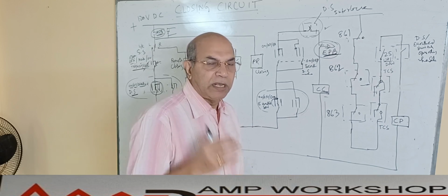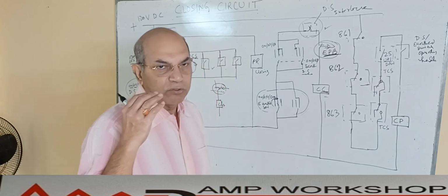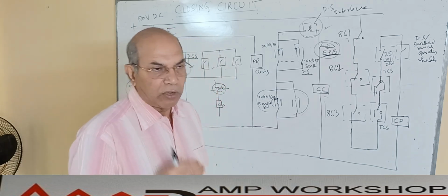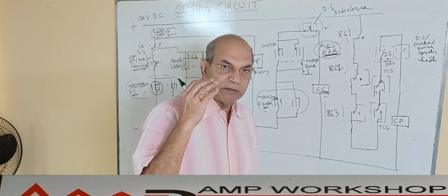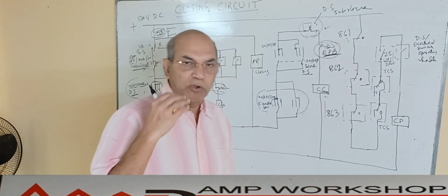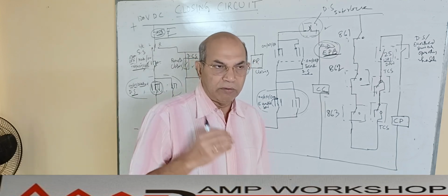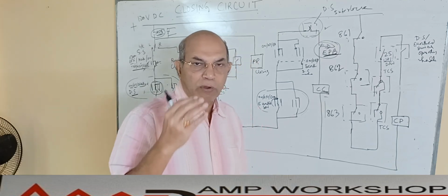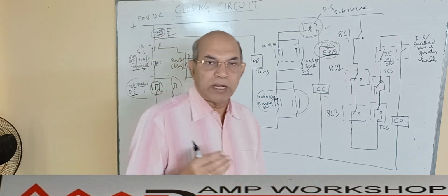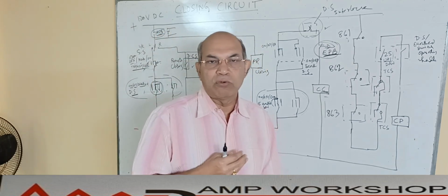In the power circuit, there is no abnormal condition, which means there is no fault in the power circuit. So how do we distinguish the fault? If there is a fault in the system, the protection relay operates immediately. When this protection relay operates, we do not wire its contact directly in the closing circuit.